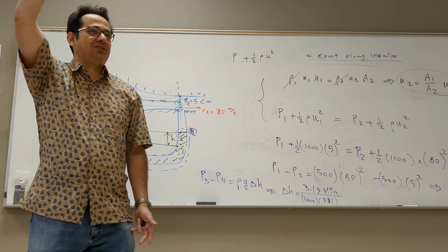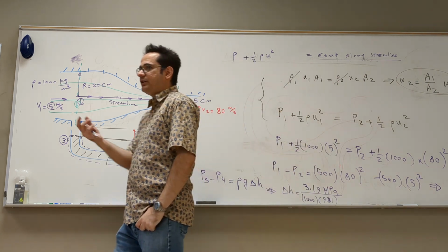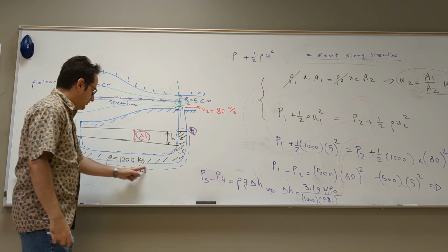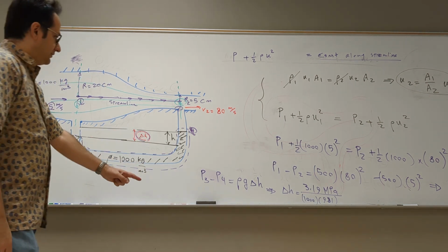Just to measure like in the aircraft, if you put a column of 12 meters, it's not even practical. Give you a very wrong number. So that's the reason they use a heavy fluid with a high density, because it divides by density of the measuring fluid, the hydrostatic problem. And then you get delta H.